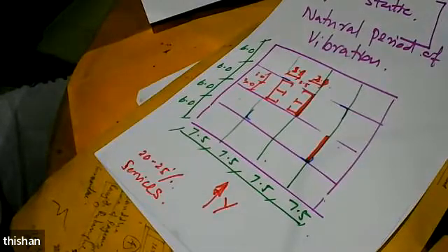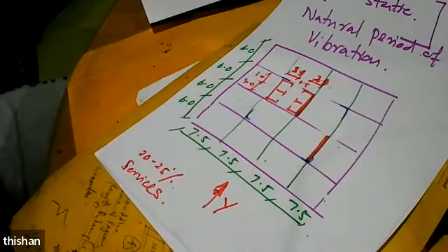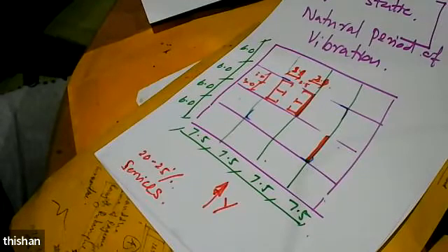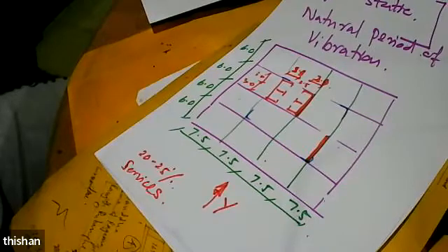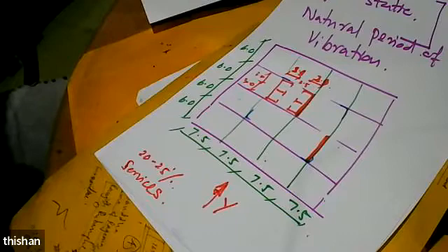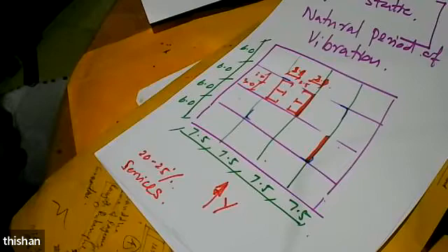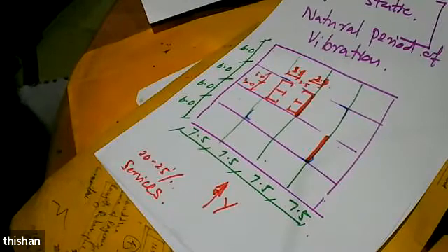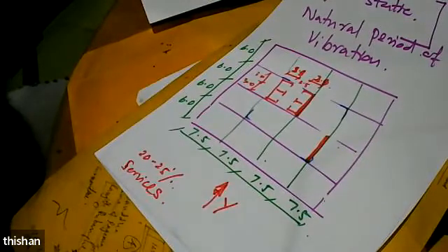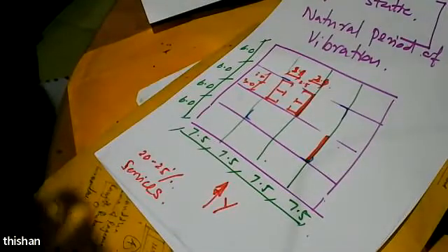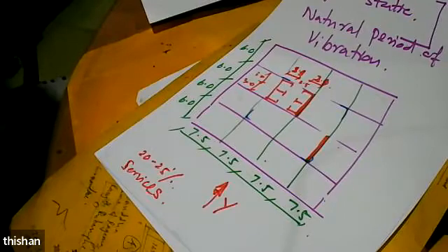But within the core, you have to have fire escape, lifts, electrical ducts, extra low voltage, air conditioning, water supply, washrooms. What else? Sometimes even a small kitchen to make it more functional. And also you might need a small storage area for the people who are cleaning the building, so that they can keep their buckets, brooms, everything within the core.